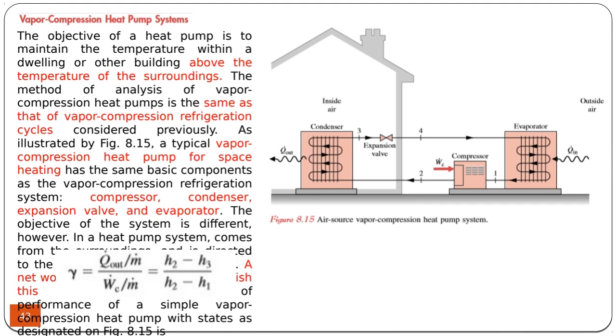In this case, you're not using the cooling part of the refrigeration system, but you are using the heat rejection of the system. If the internal unit of the air conditioner becomes the heat rejection system, or condenser, then instead of cooling the space, it's possible to heat the space by the heat rejected by the condenser.